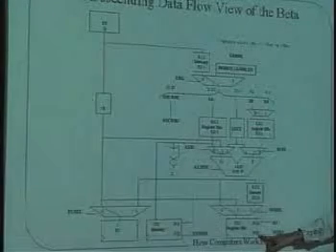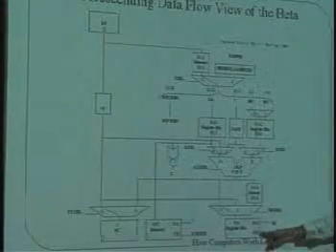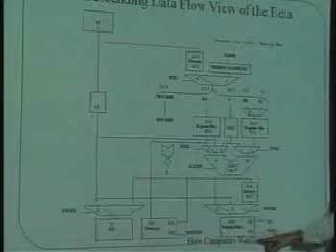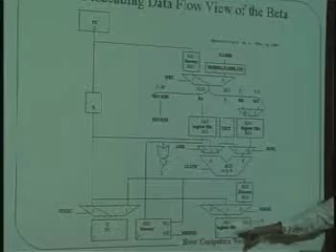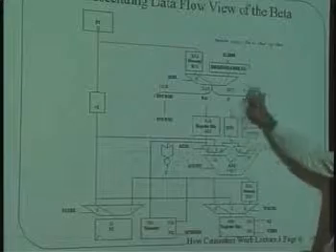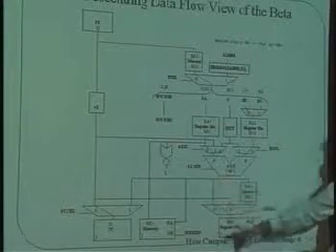The E in this register file is actually called WE for write enable, okay? And when this is high, it says, when this clock goes off, take this data and write it. If this write enable was low, when the clock went off, it would do nothing, even if there was some new data here. So it's a way of disabling the action of a write when the clock goes from low to high. Part of the idea here is that the system has no clock except for down here.